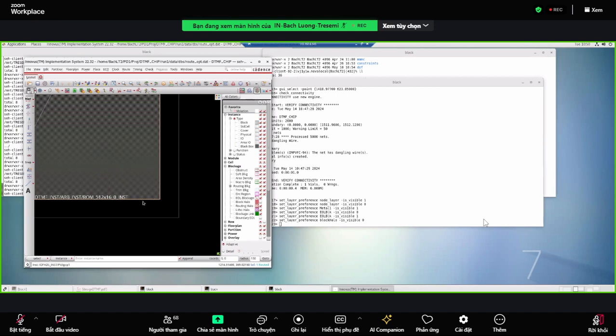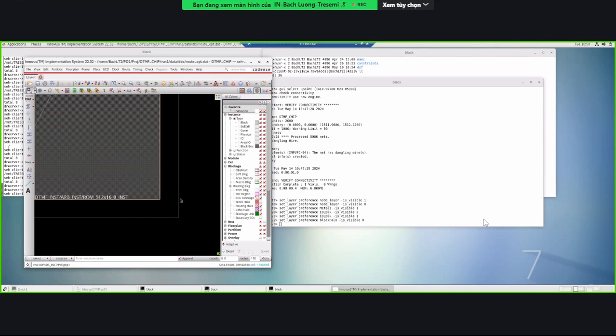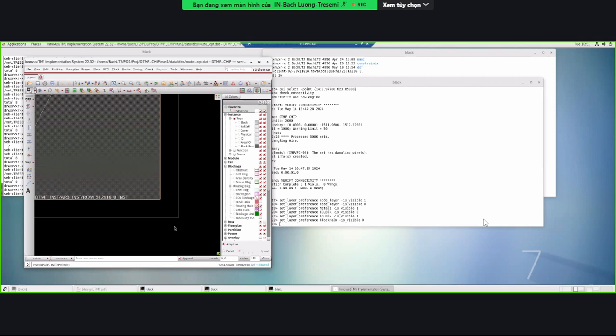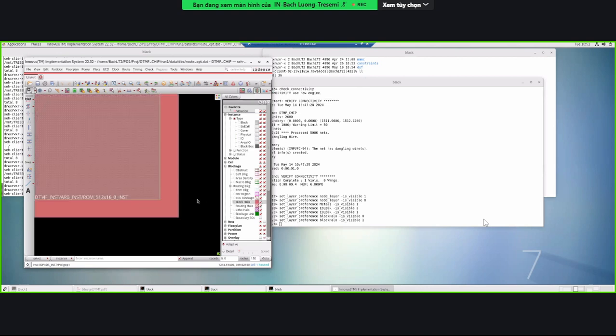Okay, so this is the macro. The macro edge is right here, and this is the die boundary, the core boundary. If you don't put a halo here, and you don't cut the row either, you have a row here, it's going to put the routes on special route, it's going to put metal one across here, and it's going to be dangling if you don't have a stripe coming in. So you need to put a block halo in, like I did. It will block it off, so there's nothing there. It cuts the row and everything, so it won't place a metal one power there, and you don't have the dangling issue. Okay, so check that.